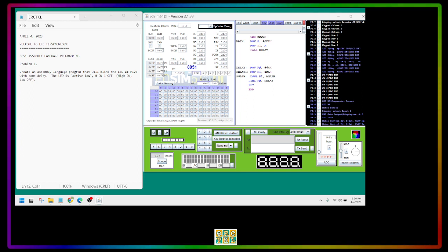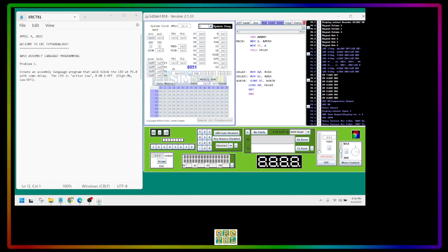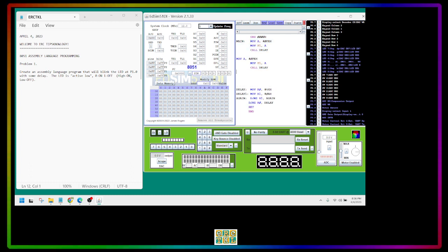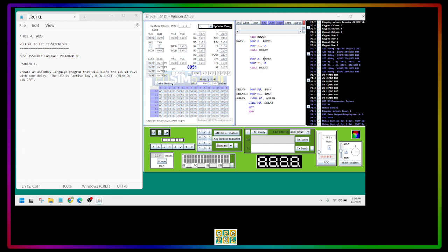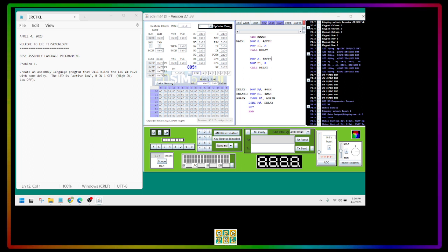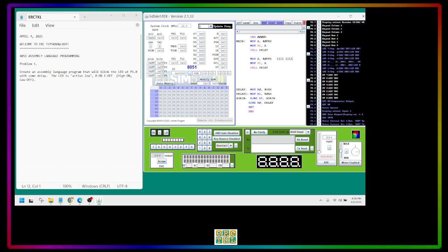Now, it's better if we demonstrate what will happen here, but let's continue this part. So after you have made the first LED turn on, then we will turn it off. And to turn it off, I just copied the first part of the program, the second line, third and fourth, and I will make this E become FF. Now you may ask why I made it FF. It's because the leftmost four LEDs will all be off, and the rightmost four LEDs will also be off.